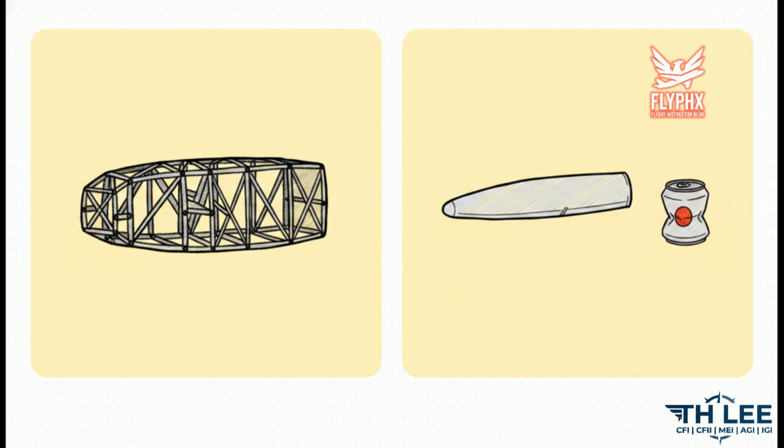As technology progressed, aviation moved to monocoque construction. This method uses stressed skin to support almost all the loads. And this brilliantly illustrates a common analogy. Think of an ordinary aluminum beverage can. It supports considerable force at the ends if you press down, but if you slightly deform the side while it's supporting a load, the whole thing collapses easily.